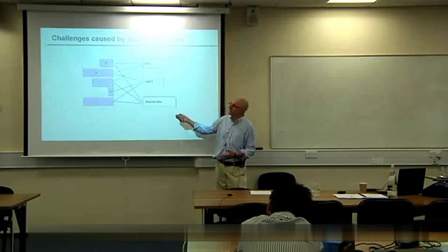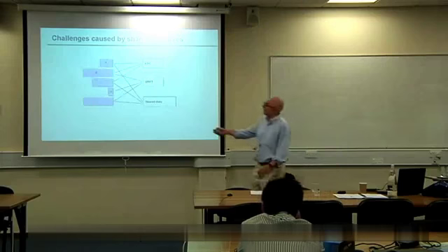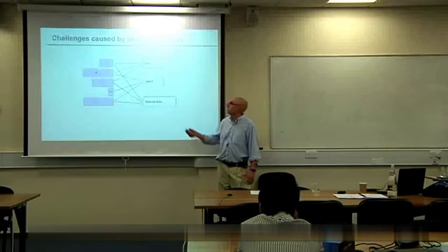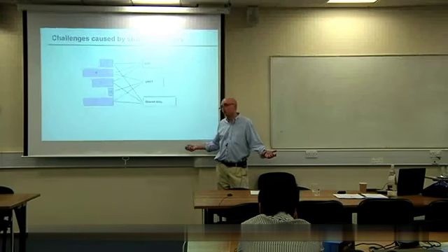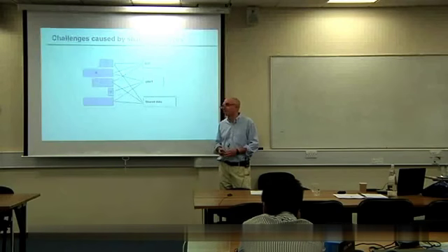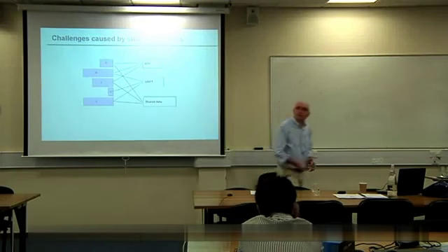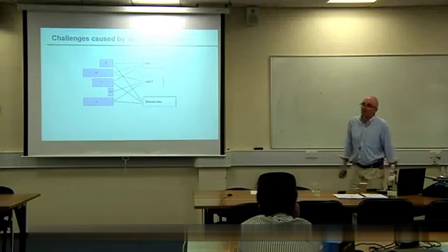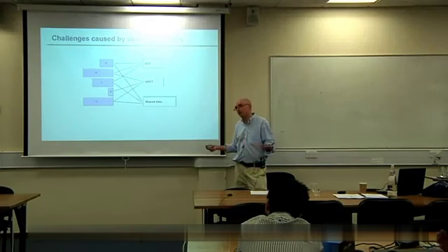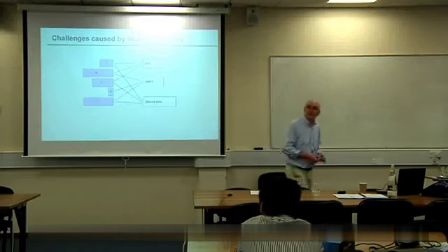As far as it's concerned, it's just continued in the same state that it was in before. Typically it'll be waiting for an ADC conversion on channel 2, but in the meantime, the ADC has been reset to do a different operation and no longer has any knowledge of the configuration that was previously used for channel 2. So this thing will basically wait forever for an ADC conversion to complete that won't happen. You'll pick that up in your timeout loop, and you can avoid some problems potentially with that if you're lucky. You can pick it up in your timeout loop, but you won't get the right data back from the ADC.